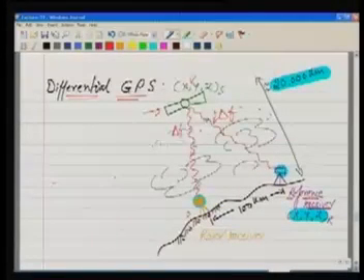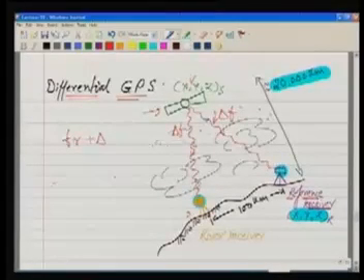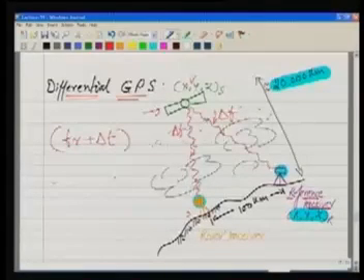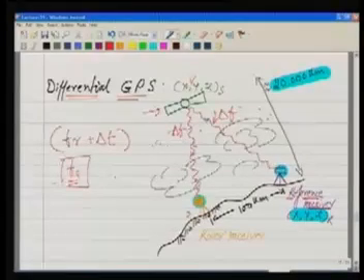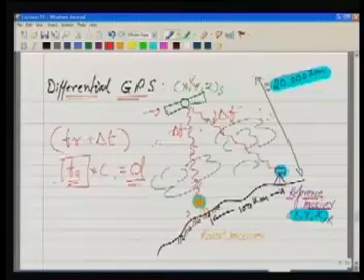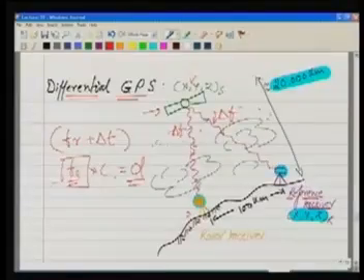So what we do here, the same time error is applied to the time measurement by the rover. If the time measured by the rover is TR, we apply the time error to it and this gives us the actual time which is without the error, and then using this we will get the actual pseudo range. So we are making use of a known position in this case, and by that we could compute the error in time, and then we are applying it to the particular satellite.